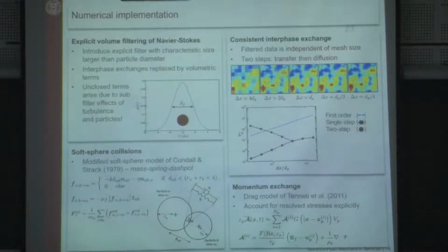If you discretize a diffusion operator and apply it on a very sharp Gaussian kernel of influence for your particle, you can spread it out to many cells at a low cost. So that's what we're doing. You have to do that in a way that's conservative. But then what you can show is that with this approach, now that the parameter is the filter size, if you refine your mesh, you should see convergence. And that's exactly what we're showing here.